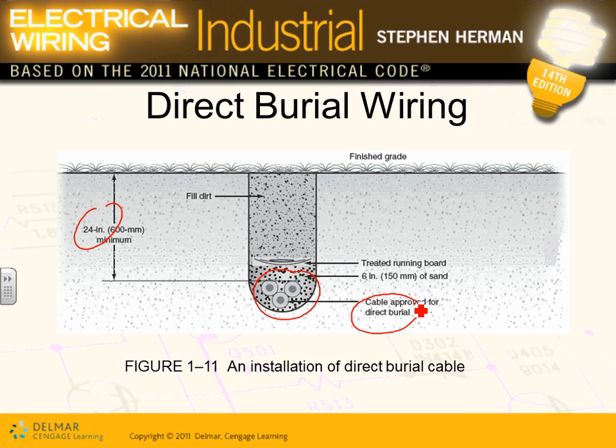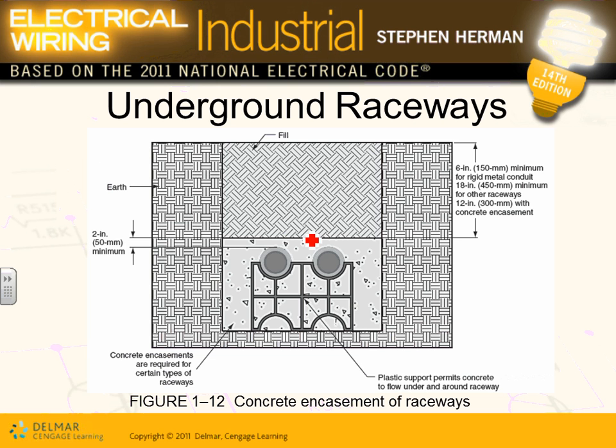You can see all the sand that they put there, and then they put the film into it. The last thing we're going to do is put a cable in, guys, and not start throwing all these rocks at the top of the cable. So they put the cables in the trench, and they put sand or very smooth fill over it, and then you put the rest of your fill, because you don't want to start throwing rocks right at the top of your cable and damaging it. These are the proper installations.